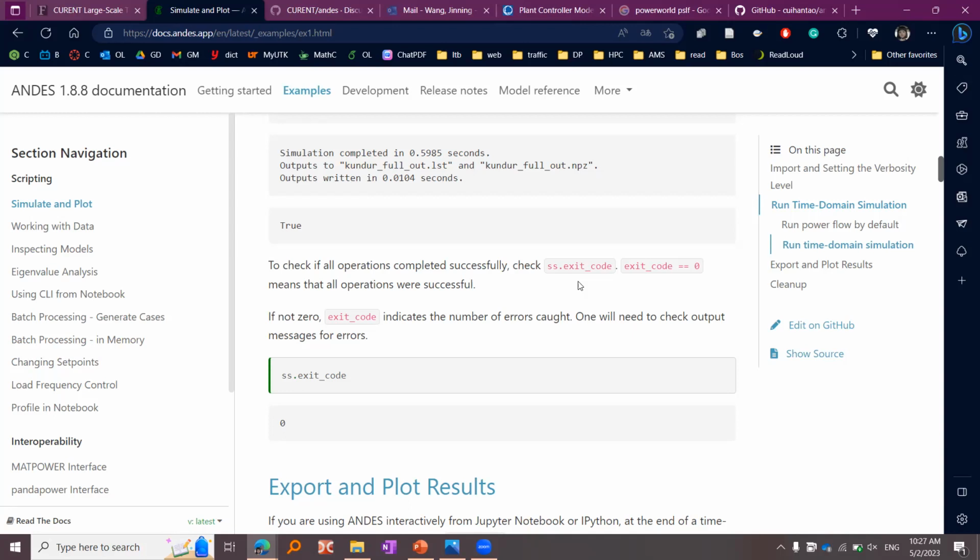Yeah, so the other thing about Andes is, although we haven't pushed that too much with high performance computing, it can take advantage of multi-core structures better than the commercial software. So it's actually faster, but it's also more robust numerically. If you want to do longer simulations, it's stable because it uses implicit integration, unlike any other commercial software.